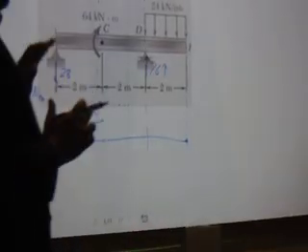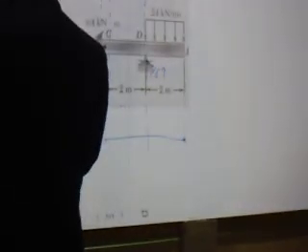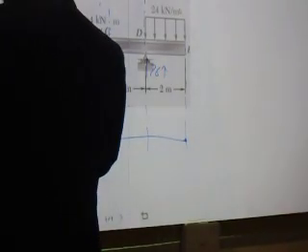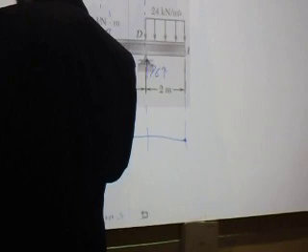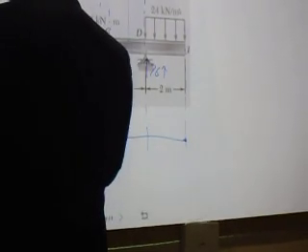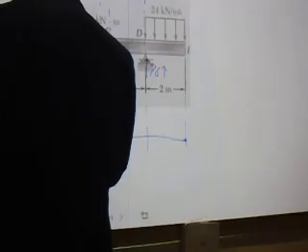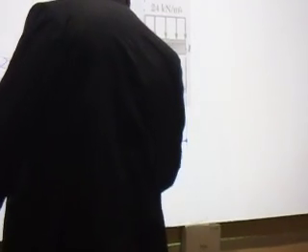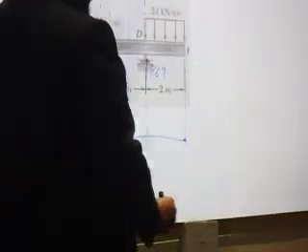Okay? It's 1/4 pi. Right. If I take a cut just after C, what will I see? A 64 that is smiling back. 64 that is smiling, positive, minus 28 times 2. So this 64 minus 56, this is what? Exactly 8 kilonewton. This is 8. Okay?